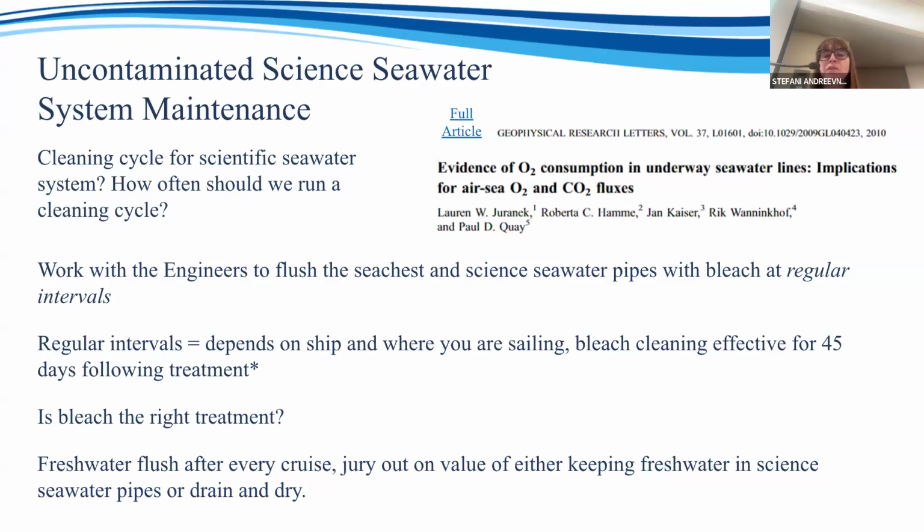Freshwater flush after every cruise. And it's another interesting part of the discussion, freshwater flushing through the piping system. Just make sure you're freshwater flushing everything. The other thing I should say about the bleach treatment is make sure your sensors are isolated and not exposed to bleach. That's not a good idea. Many of them don't like that, so just make sure they're isolated.